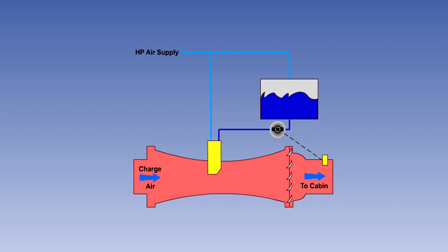However, at the high cruising altitudes used by modern transport aircraft, the air is very dry. When operating at high altitudes for long periods of time, it may be necessary to increase the moisture content of the conditioned air from the 1 to 2% relative humidity of the ambient air to a more comfortable level. The component used to do this is the humidifier, a typical example of which is shown here.